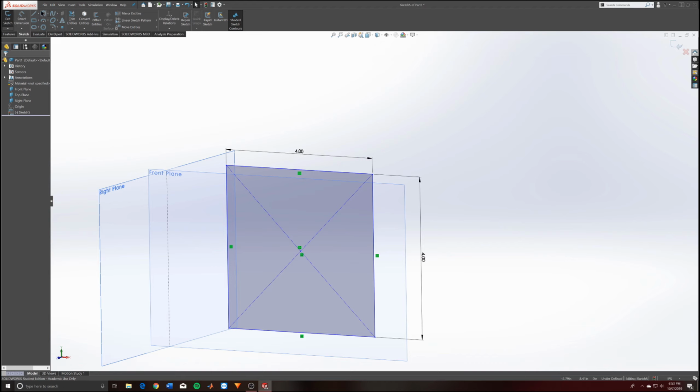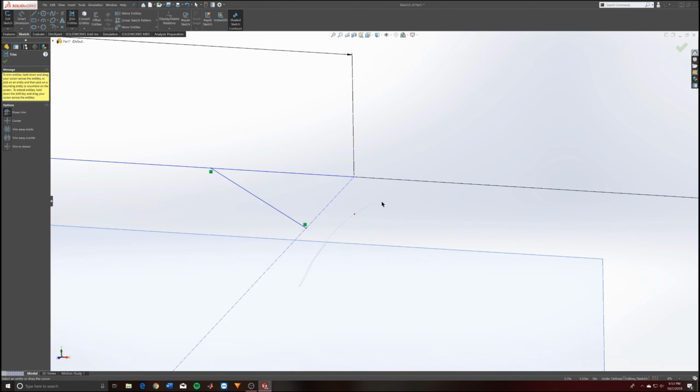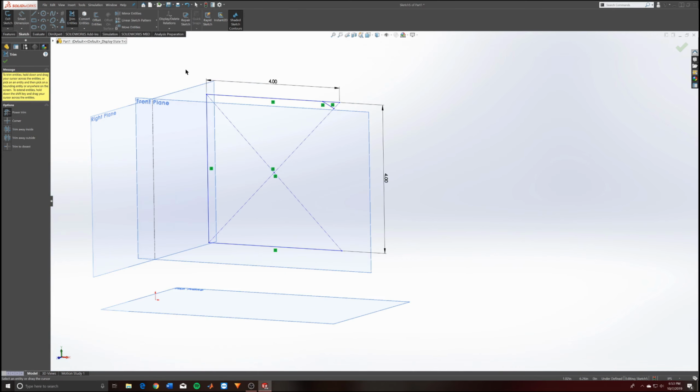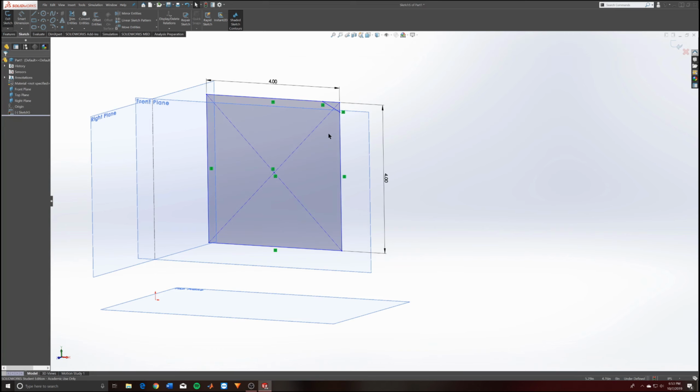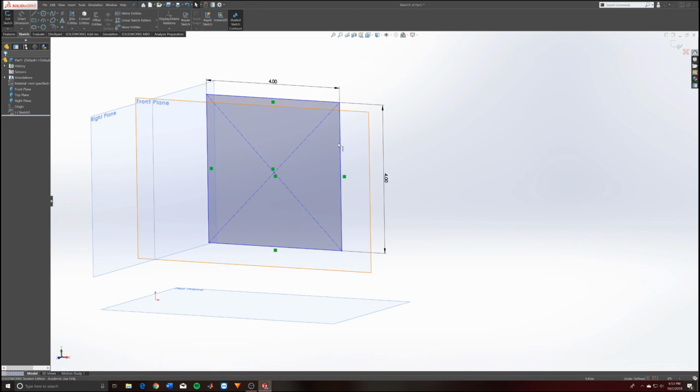If this was not completely closed, where it was like that, now you can see the drawing is not completely closed, so it's not filled in. And what I was just using right there is trim entities. Imagine it as a scissors, and you can draw through lines and cut them. So if you want to quickly delete lines, you can do it that way. Otherwise, you can just hover, click on a line, and hit delete.